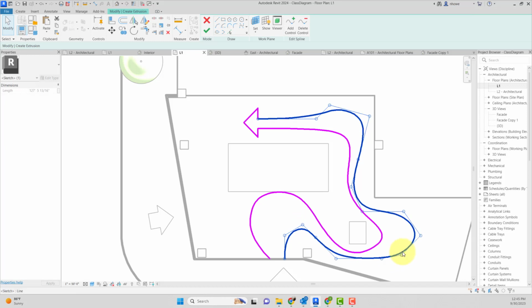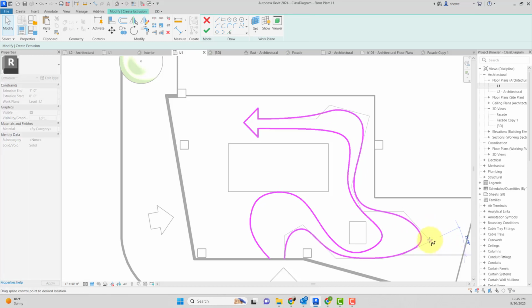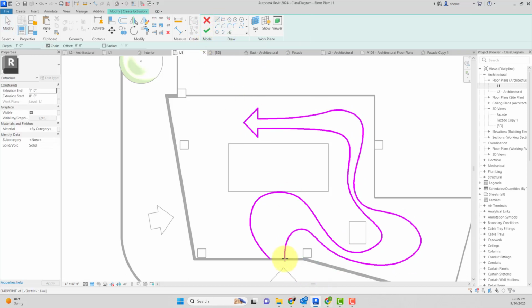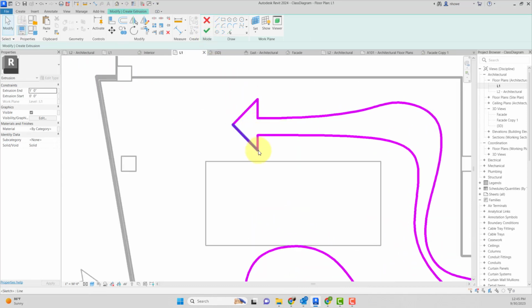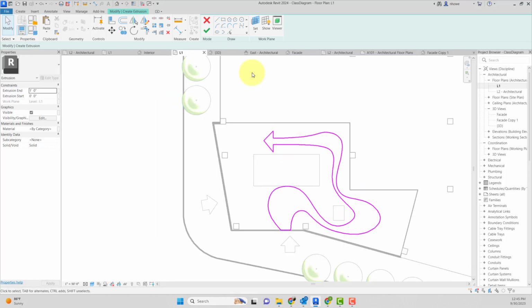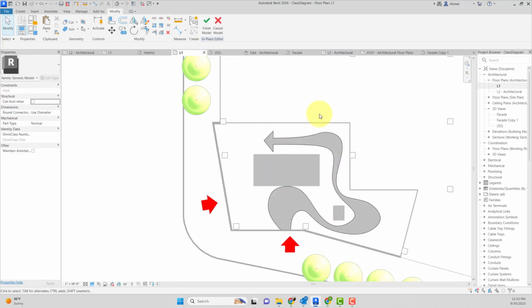Make it not so, I would say pinchy, and not pinchy as in this, pinchy as in like when that curve's not very nice. So it's kind of adjusting these to really let it flow. Is a good way of going. So you do need to always close these extrusions or it won't work. Let's say some things right here. Make sure that kind of feels even. And I can like there, done.